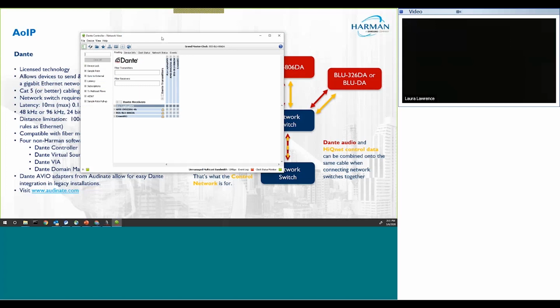I have my own laptop here, which is running another software program from Audinate, which is called Dante Virtual Sound Card. So this item here labeled Al's Laptop, DVS, that's the Dante Virtual Sound Card in my laptop. And I can do anything from stereo 2-channel all the way up to 64-channel by 64-channel on this Dante Virtual Sound Card.